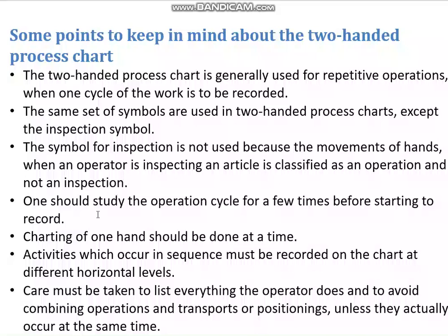Then while you are preparing this two-hand process chart, you should study the cycle of operations a few times and then start recording. You should not start recording at the moment you come to the place. You observe it for some time, a certain number of cycles, and then, when you have understood the cycle, from where to where you should record, then you should start recording.